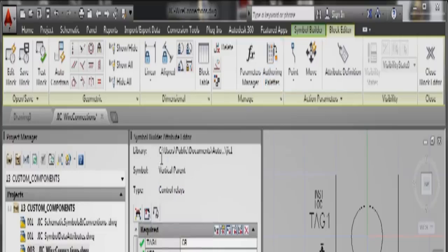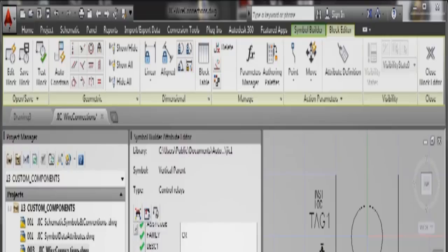I'll close the block authoring palettes like so. Now the reason that it hasn't updated the wires is because we have no wire connections on this just yet. They're right here. So we can see wire connections there, direction, style. So what we need to do is set some new wire connections.